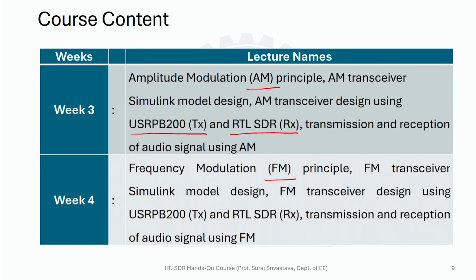In analog modulation, whether it's AM or FM, these schemes in general are not robust towards noise. But we'll see that these analog modulations are robust toward channel impairments like frequency offset or phase offset. Because of this robustness towards frequency and phase offset, they are still preferred in many analog communication systems. So in summary, the analog modulation schemes are not robust towards noise, but they are robust towards phase and frequency synchronization.